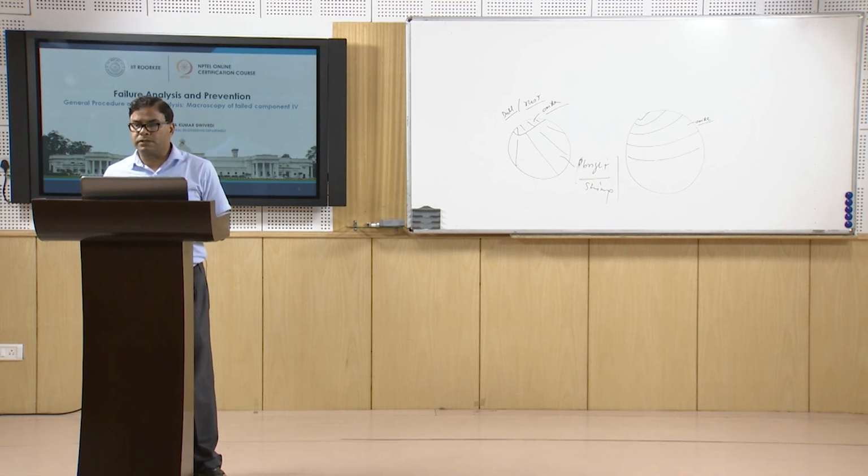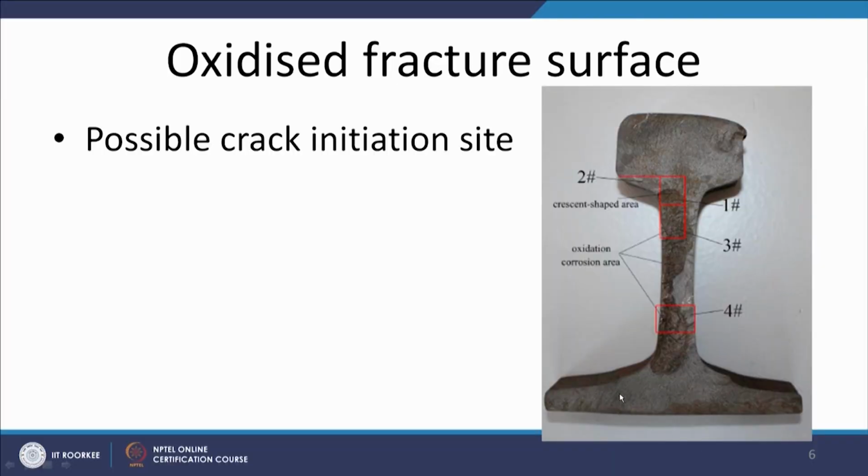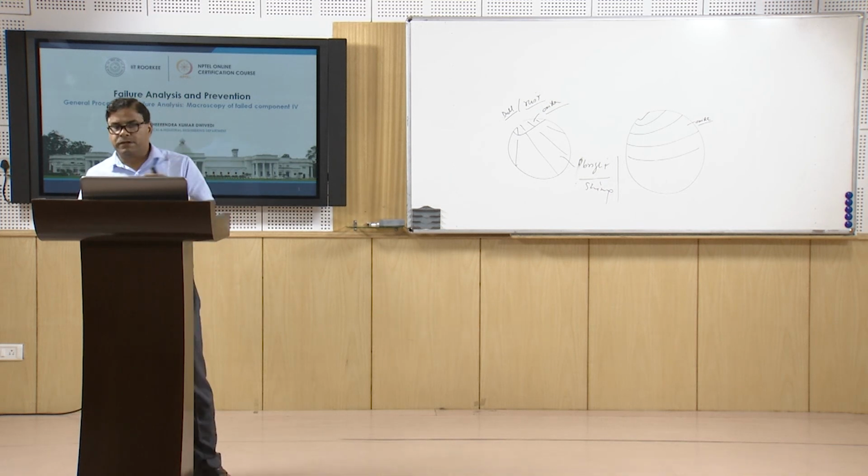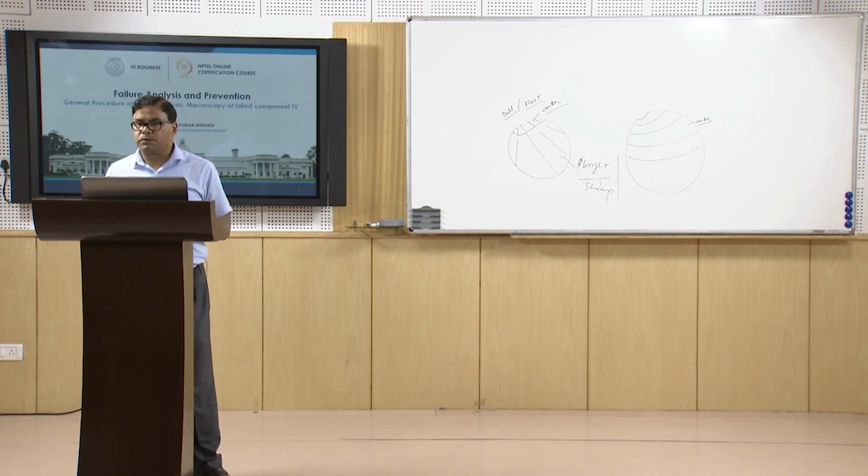So, this surface also shows these are the freshly fractured surfaces, which are the bright ones as compared to the others which are dull. So, the most dull surface is this, which is suggesting the possibility of the initiation of the crack. Other surfaces which are somewhat less dull will indicate that these surfaces have not been exposed that long to the environmental or corrosive conditions.